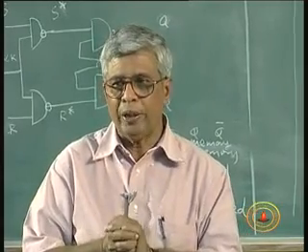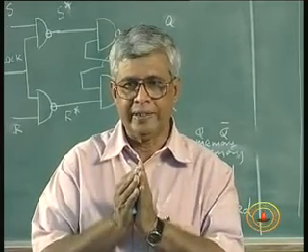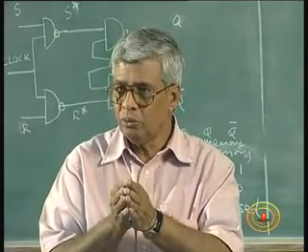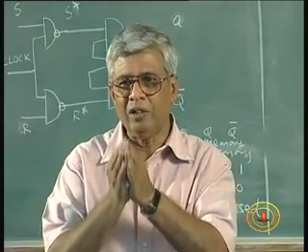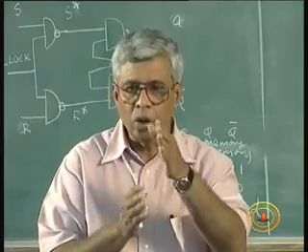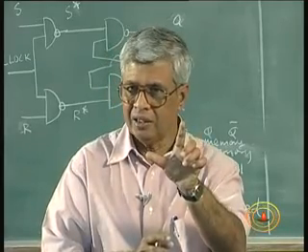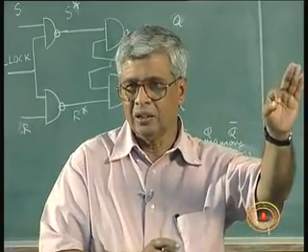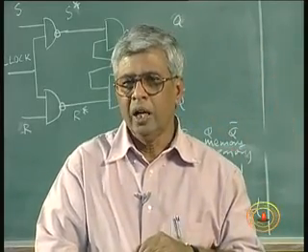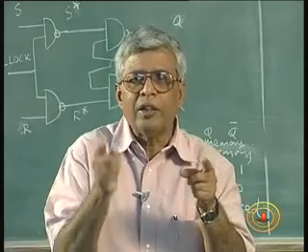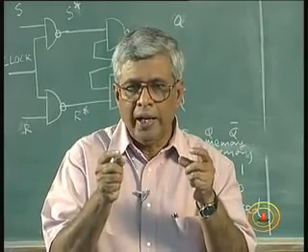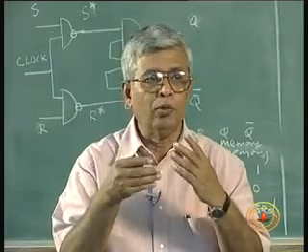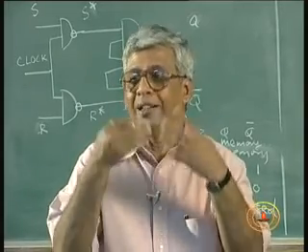So the best way would be to make any changes in the input when the clock is low. So when the clock becomes high, the values get absorbed or stored in the latch. They remain in the latch for use in the next circuit or subsequent stages. And during that clock high, you never try to change the input. And again, when the clock goes low, if you want, you can change the input one more time. If you have a reason to change the input, do it at that time.